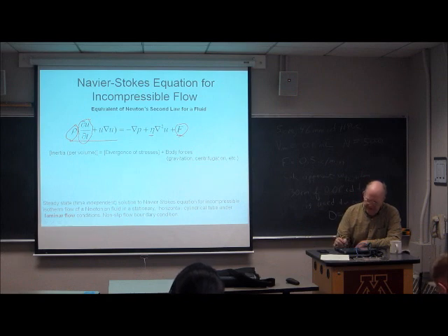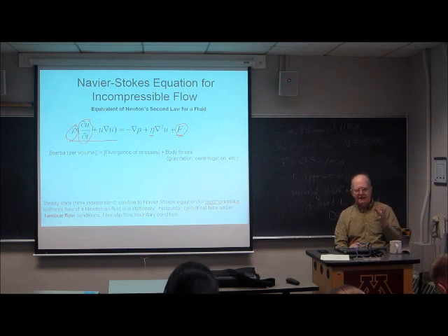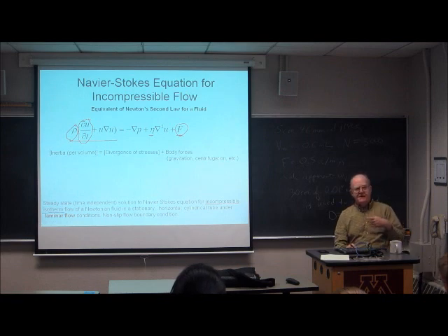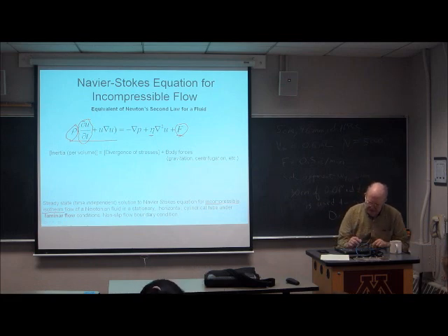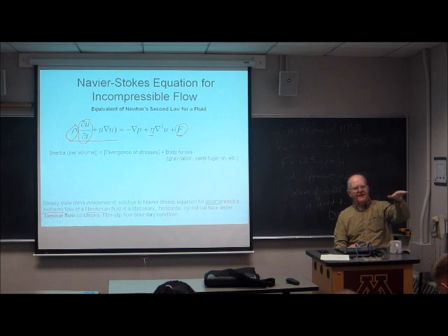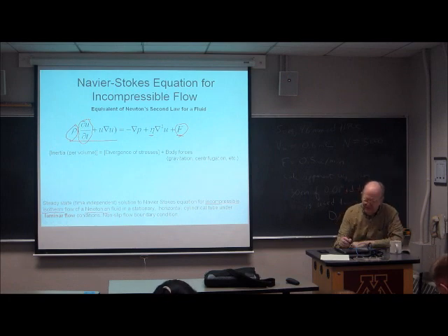We're applying it to an incompressible fluid, so theoretically this has to be not a gas, but a liquid, and not just a plain liquid, but a highly incompressible liquid. We have to disallow any heating of the fluid during the flow process. It has to be a Newtonian fluid, meaning the viscosity is independent of velocity. The tube has to be horizontal. It has to be like so, not like this. And if it's horizontal, then gravity doesn't matter.